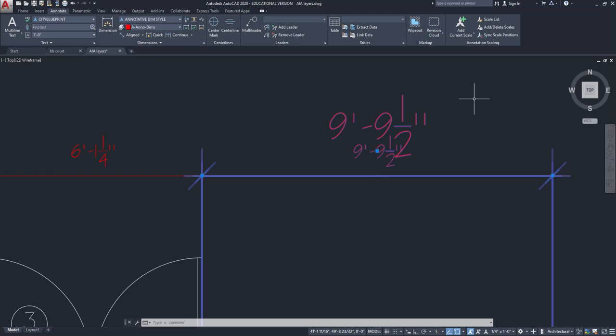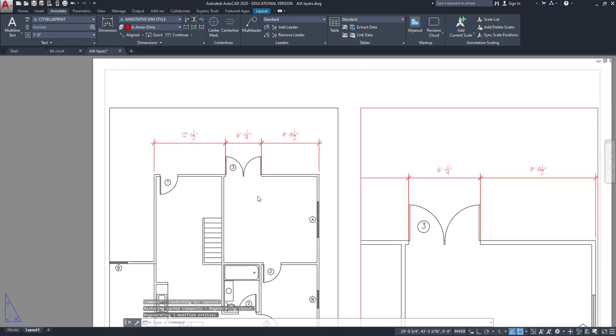We had to do it manually. So this ability for AutoCAD, the annotative ability to flex our text to make it smaller and larger depending on the scale we scale it at, that's kind of what annotative text is all about. Okay, annotative text is AutoCAD's ability to make our text larger and smaller to accommodate different scales in paper space.